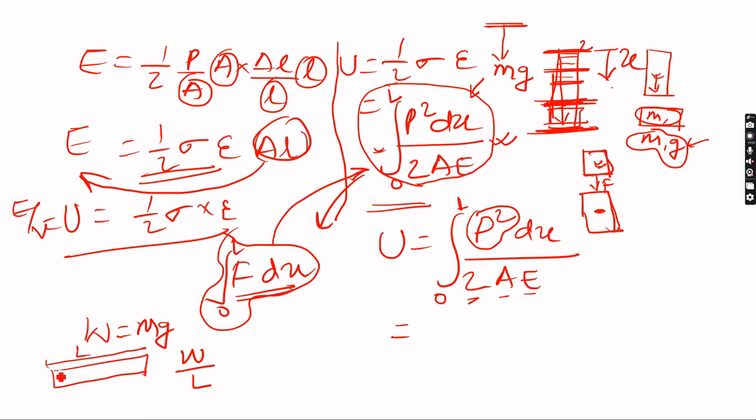As length is increasing, your mass is increasing. So if W by L is there and you multiply with x here, if x is equal to L, what will happen? This will be cancelled, then your weight will be W. If x equals L by 2, what will be the weight? L by 2 means up to here. So W by L into L by 2, this will be cancelled. The weight will be W by 2. So up to here only half mass you are considering, and due to half mass the weight will be mg by 2. So this is a linear variation.